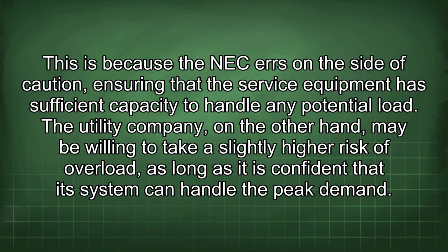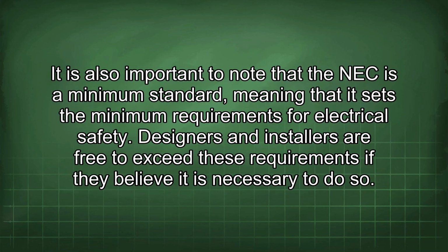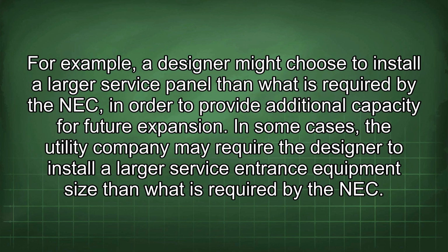The utility company, on the other hand, may be willing to take a slightly higher risk of overload, as long as it is confident that its system can handle the peak demand. It is also important to note that the NEC is a minimum standard, meaning that it sets the minimum requirements for electrical safety. Designers and installers are free to exceed these requirements if they believe it is necessary to do so. For example, a designer might choose to install a larger service panel than what is required by the NEC in order to provide additional capacity for future expansion.